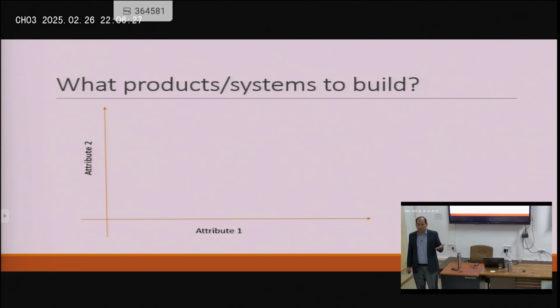So, the general convention, which we often violate, is that the origin is the utopia point, as they say, is the best point. Means that attribute 1 is such that we want to minimize it. Attribute 2 is also something that we want to minimize, okay? So it could be weight and cost. We want to minimize cost, we want to minimize weight, okay? And it doesn't take away from generality, because even if it's something that you want to maximize, let's say power, you can just reverse the axis and somehow visually you can still show it at the origin. So it's not even a problem, okay?